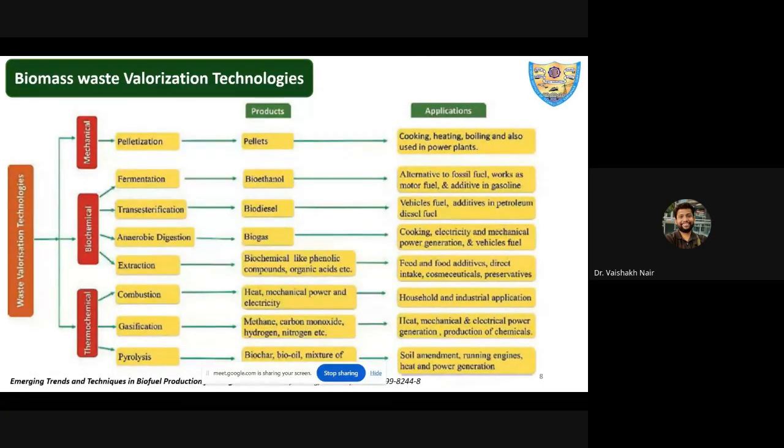So if you go for slow pyrolysis, that is basically heating at a higher residence time, that is 1 to 2, 3 hours. So you basically get more of the solid material. So biochar becomes basically the main product. Otherwise, normally people focus towards the bio-oil point. But again, I will consider this here slow pyrolysis. So you'll see biochar is basically considered because it is again used for the application.